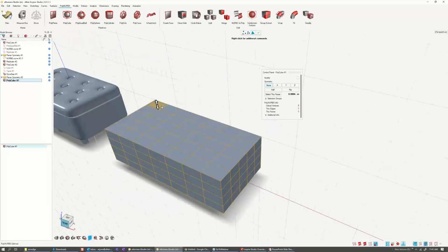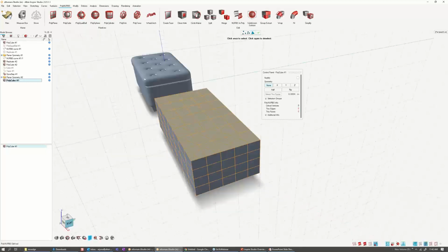So instead, you can also go to the top view and just use the advanced selection as I was showing before. So let's go to advanced selection, select this and select the last one. And then when I hit the arrow, it's going to select all of them in between. I can propagate. If I hit this, it'll propagate all the way. So I want to just go once. So I can do Alt click to go once, but it selects everything. So let's again select this and hit the arrow, select this, hit this arrow, and we're going to select the remaining objects this way. So I have these. So the reason I selected the top is I want to extract these faces.